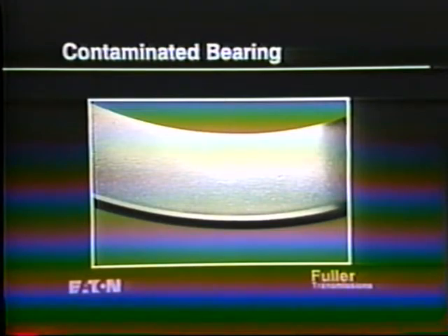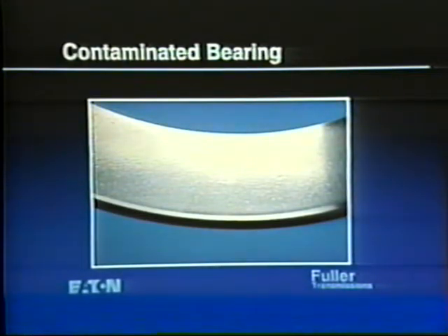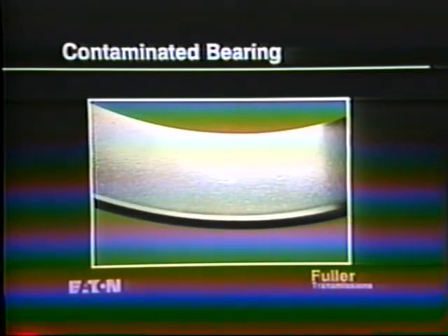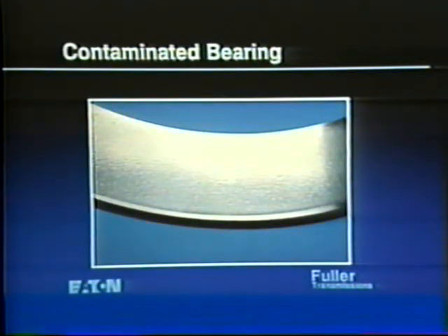Contamination can enter the bearings from two sources: from improper handling of the bearings during repair, and from inside the transmission, such as metal chips resulting from clashed shifting. Avoid contamination during repair by keeping the bearings in their containers until ready for installation. Reused bearings should be thoroughly cleaned, oiled, and wrapped with a protective material until ready for use.